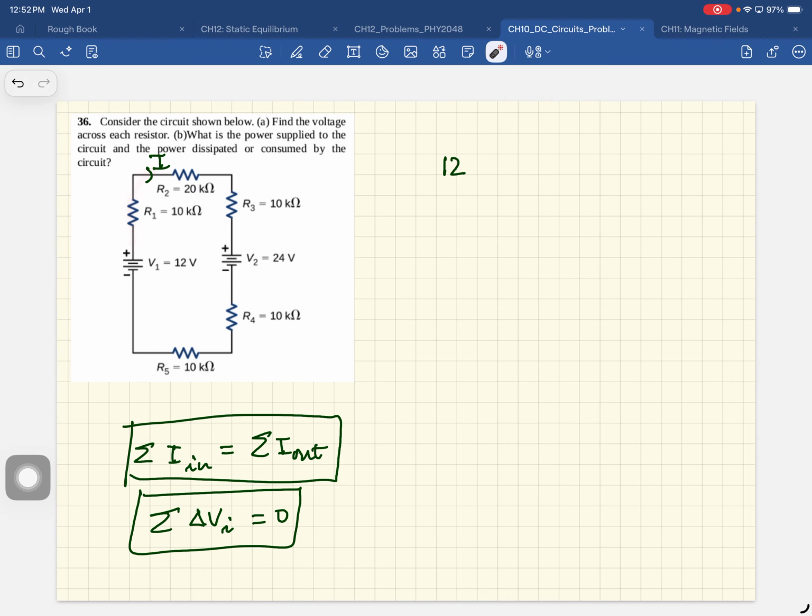Then you're going across this element. Current flows from a high voltage to low voltage. So when you go across this, the change in voltage is negative IR1. What is the next term? Negative IR2. The next term? Minus IR3. Somebody else, what is the next term? Would be plus IR4, I guess? Or plus IR4? You're going to ignore the battery? So it'd just be V2.